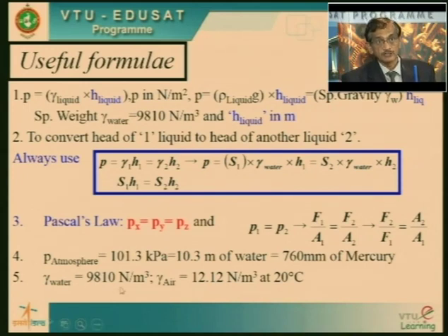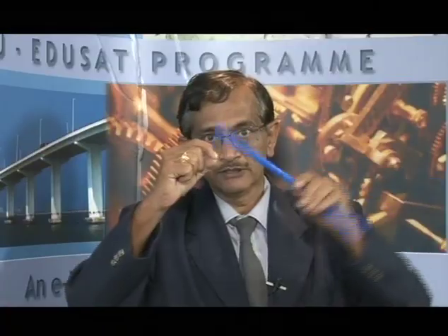We have discussed in the previous lecture one small problem on hydraulic jack. That is totally depending upon Pascal's law. Today anyway we are not solving any problem on this. Px equal to Py is equal to Pz. That illustrates the pressure intensity is transmitted equally in all directions. Any particle as here is going to give Px, Py and Pz. In all the three directions it is going to put equal pressure.